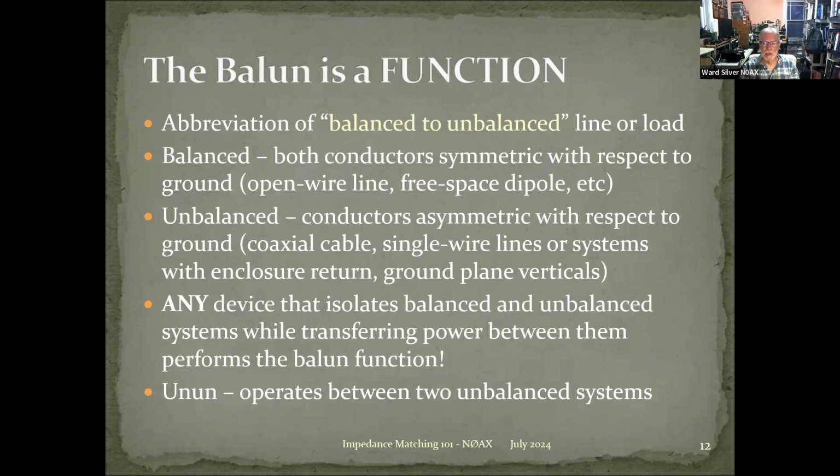And an unun, which you will also see, is something that operates between two unbalanced systems. You can buy little impedance transformers with a PL259 on each end, and you screw on your cables. That's an unun, because both terminals on each side are asymmetrical electrically.